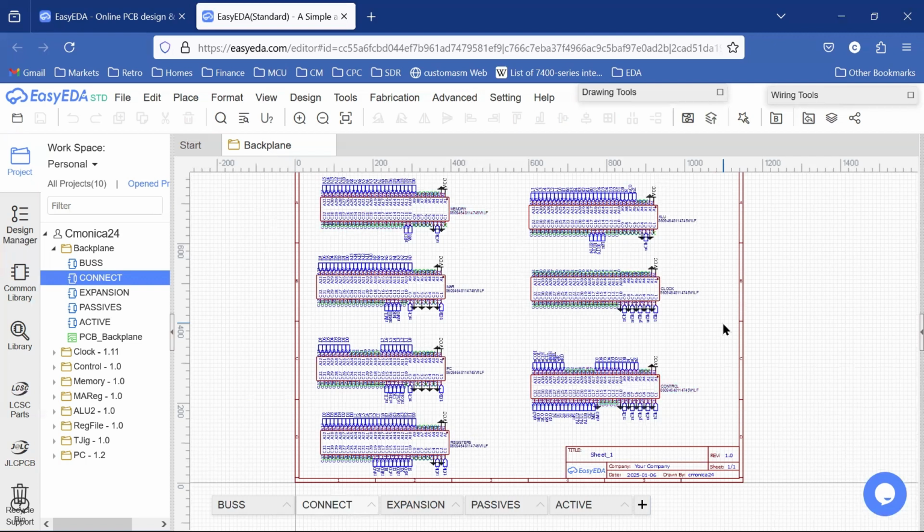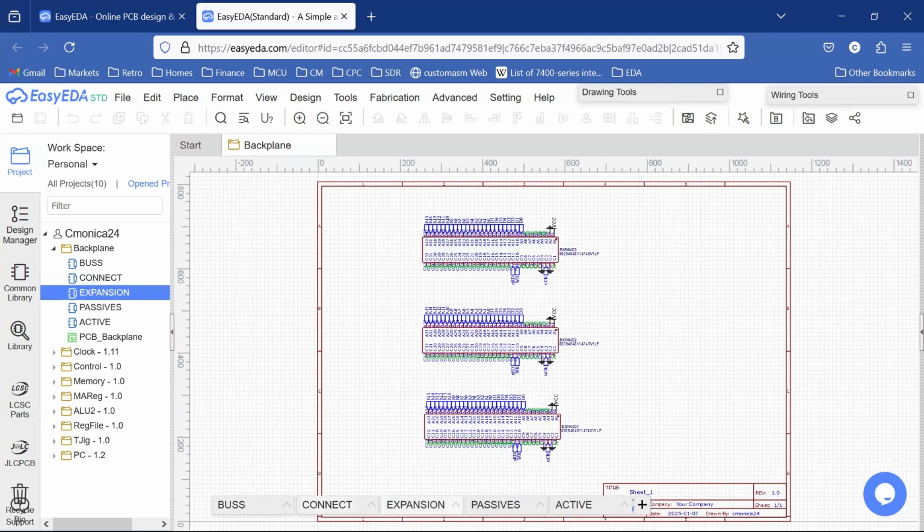So those are two of the first complications that we had. One, I made that error with that C10 pin, not making the control signals all be completely identical on each card. And then the control signals not being in the same place on each card edge. So those were the first two complexities that I encountered. All right, that's going over to expansion cards.